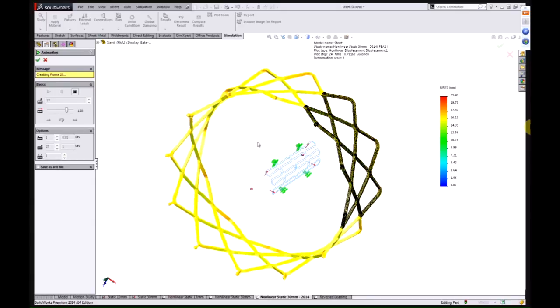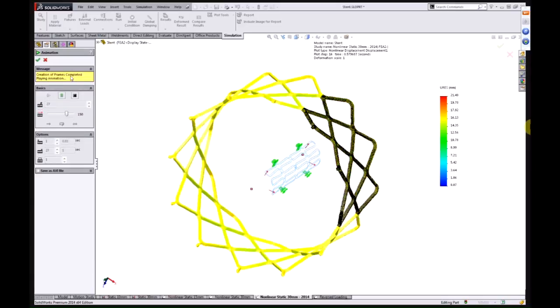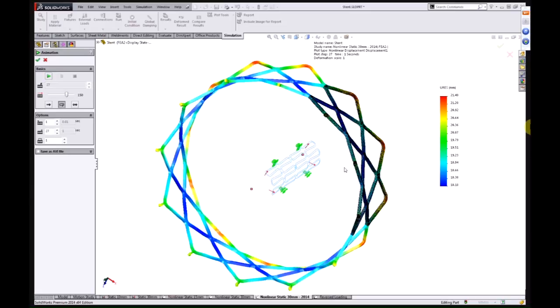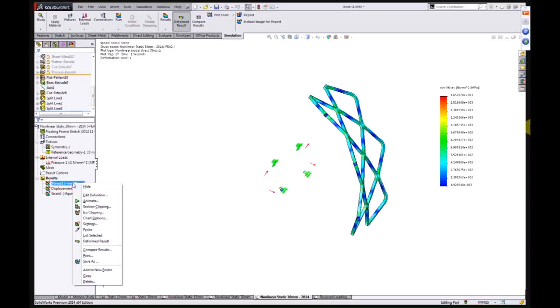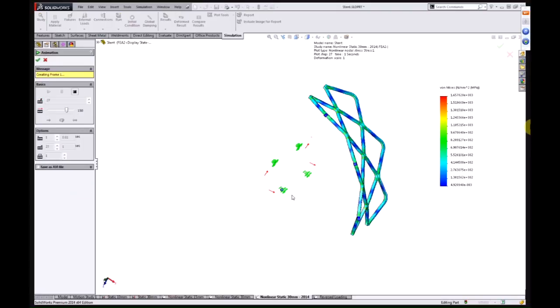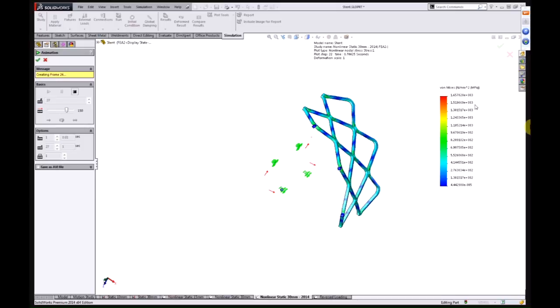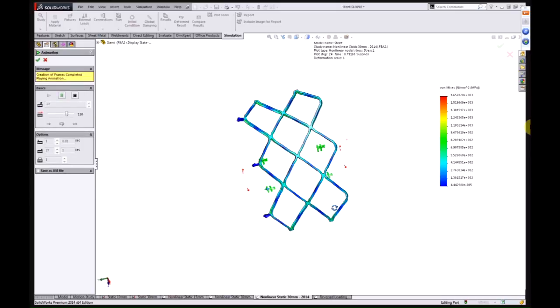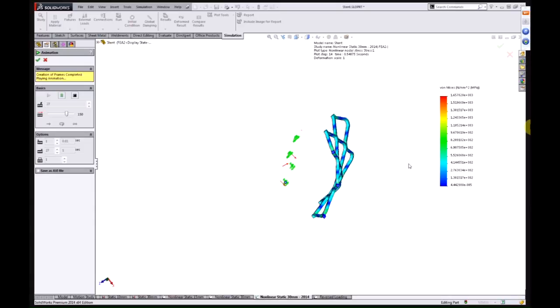In this case, we would have significantly exceeded any sort of failure stresses of this material, and so we'd predict some sort of failure long before it got to this size. But we're talking hundreds of percent of strain that's available when we distort this outwards. See how the shape of it is changing as it's being asked to go out there. So pretty extreme displacement.